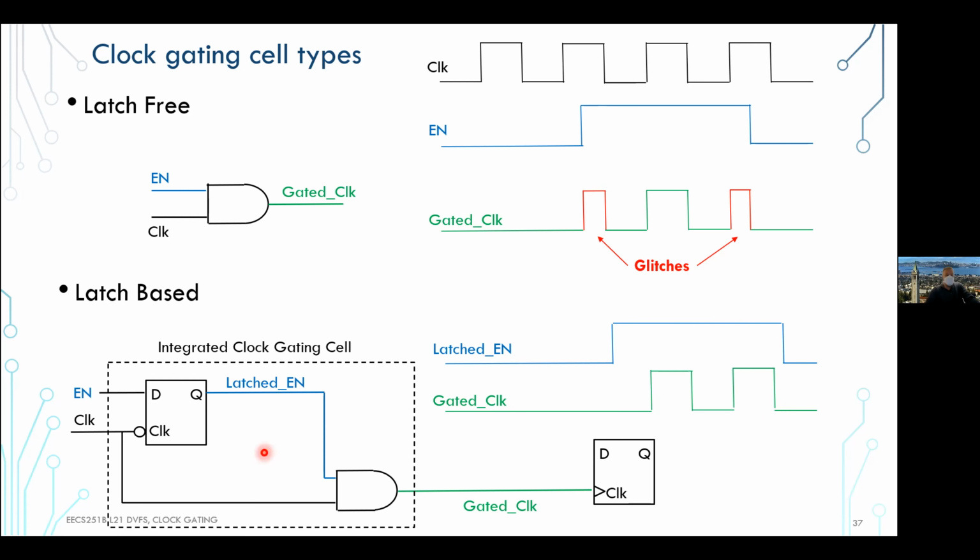This very nice behavior definitely depends on the delays on these paths, right? So you can't just, well, you can, but with great risk, let the tool go and put a latch somewhere, put an AND somewhere, and then hope that this is now your gating cell, because you may get different wire delays. Who knows where this is, right?